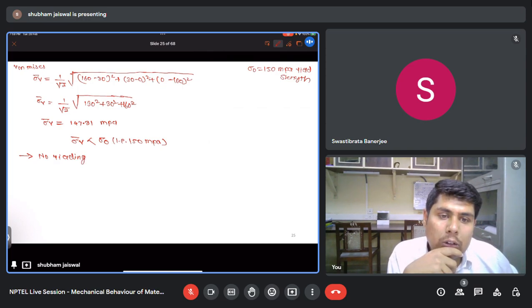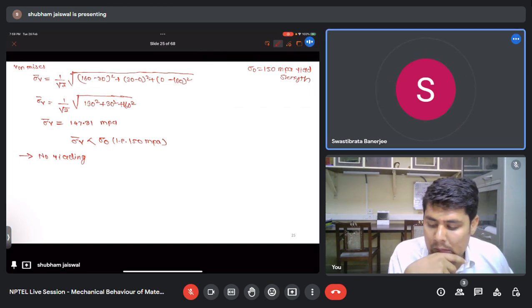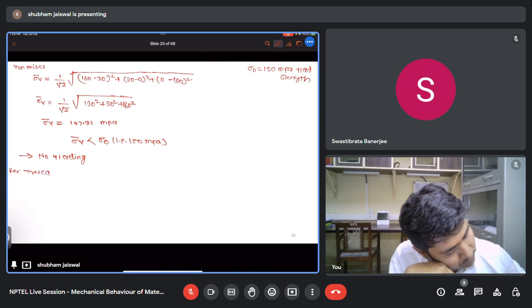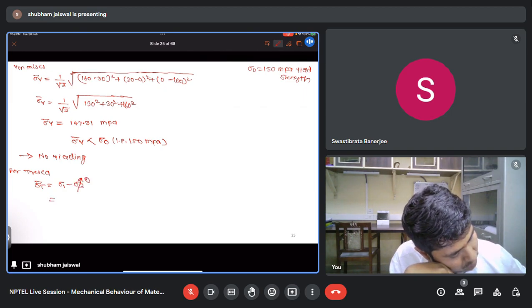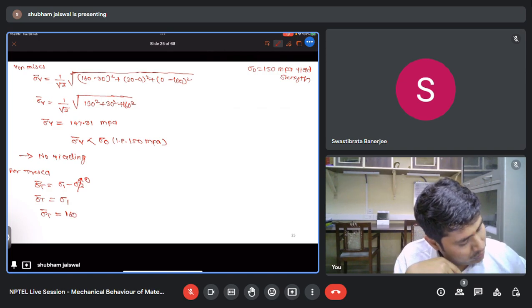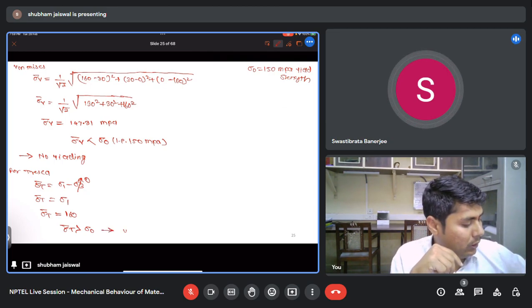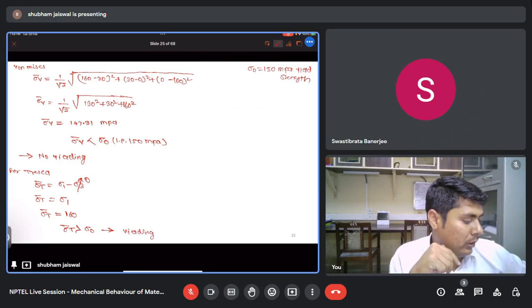Are you getting my point, Mr. Swasti? Yes, sir. Now for Tresca, sigma 1 minus sigma 3. Sigma 3 is 0. So sigma bar T is sigma 1. Sigma 1 is 160. So sigma bar T is greater than sigma naught. So what will happen? Yielding occurs. Yielding will occur.